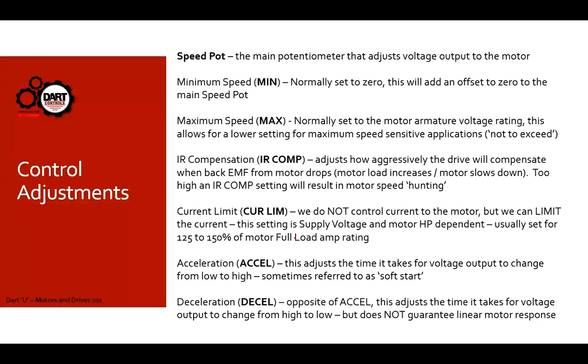Acceleration is an adjustment that's also called a soft start. We may turn a control on, or we may want to run the motor faster by adjusting the speed pot, rather than respond to that input change immediately. The accel will actually allow us to ramp up softly, from zero or from the previous setting, and this is desirable in some applications. If you think about some bottles on a conveyor, if you want to speed that conveyor up, you don't want it to jump up in speed, otherwise we'll knock all the bottles over.